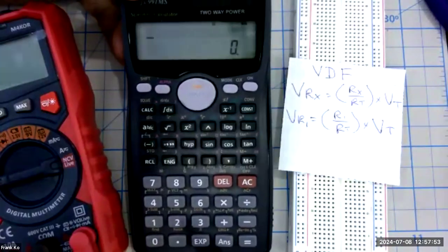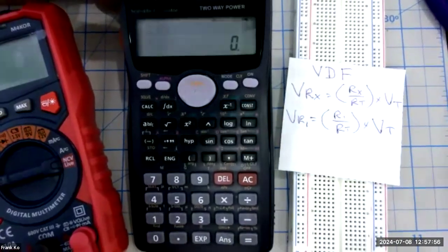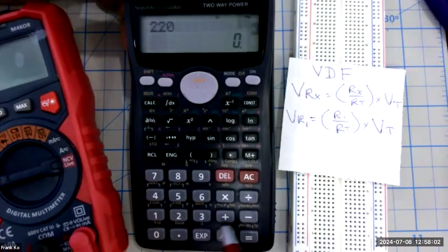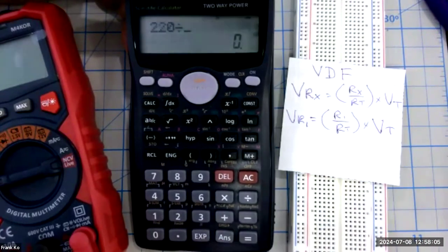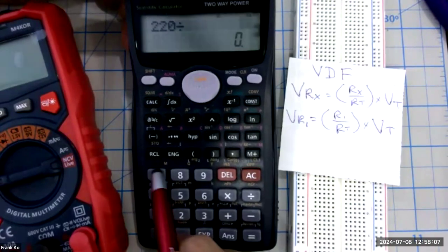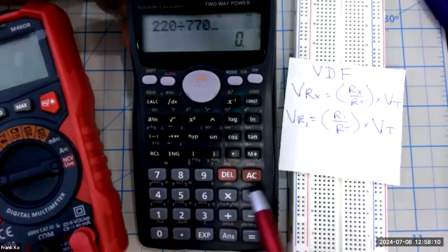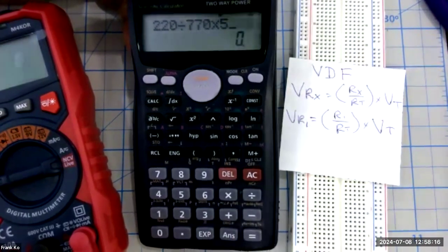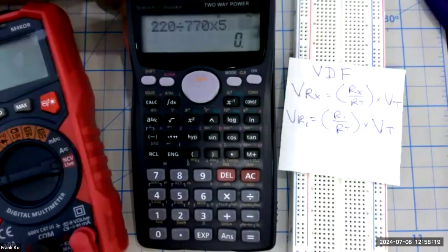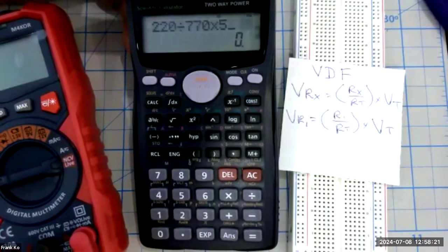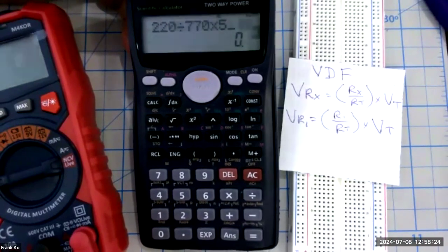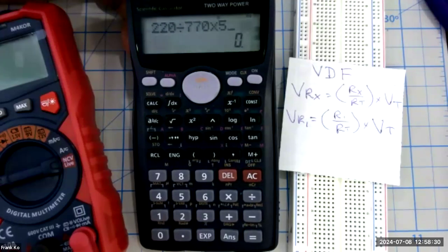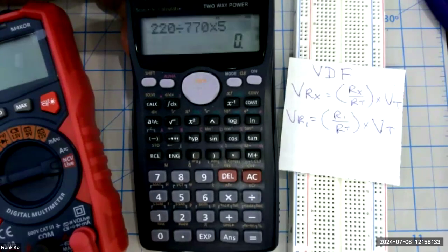Let's go ahead and do the calculation. We're going to start off with 220 ohms, and we're going to divide that by the total ohms, which in this case is 770 ohms. So 770, and then multiply this by the 5-volt source, and we should calculate a number. You should do this calculation. Don't wait for me to pop up the number for you so you can just copy it down. You should do this on your calculator. This is a hands-on drill. And who needs to learn this? Me or you? You. So who needs to do this? Me or you? Both of us. But you need to do this before I show you the answer.